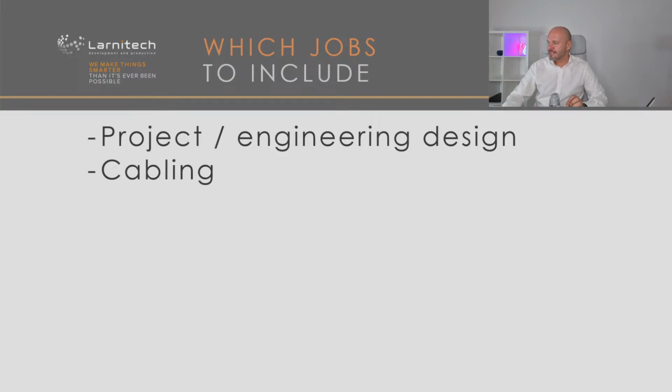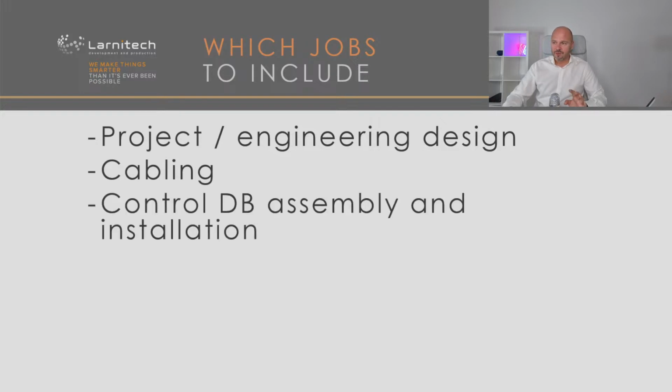And third is control DB. So we have a control distribution board, and this is really very separate. So sometimes, for example, cabling can be done by local electricians, but control DB should be done by professional installation company, because control DB is actually everything important in this home automation. So control DB assembly and installation should be separate,